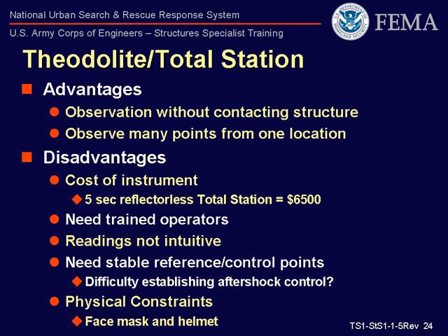The significant advantage of using a survey instrument for monitoring is to observe displacement at a safe distance from the hazard. It is also possible to detect displacement in several locations from one observation location. Some of the most difficult disadvantages are the cost of the instrument and the availability of trained personnel. There are also other disadvantages that may limit the effectiveness of the monitor plan. These are unaccounted displacement of the instrument or coordinate system and the inability to use the instrument with full PPE.